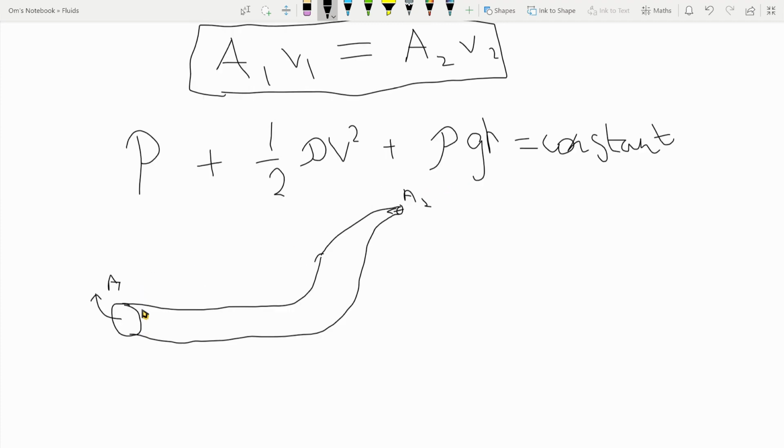So over here you can think that the fluid is actually exerting a pressure in this direction. Although technically speaking the fluid is exerting a pressure equally in all directions, what we're actually concerned with over here is the pressure exerted in this direction. And the reason for that is there's most likely an external force over here that is pushing the fluid in this direction and doing work on it. But what we're concerned with over here is the work done by the fluid, and that pressure is actually in this direction.